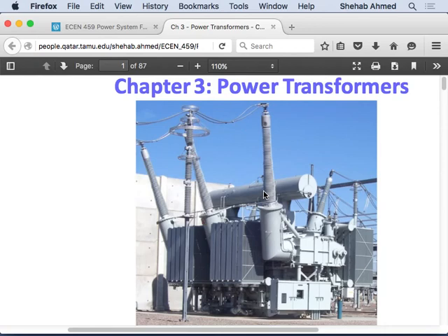And then if you do that and you add a fan around the radiators, for example, so these radiators maybe on the side, like your car radiator, if you open up your hood, you'll find your car radiator has a fan right next to it, right? So at some point, initially when you start, maybe the fan is not running. After a few minutes, then you'll find the fan running, right? So this is an additional way of forcing the radiator to cool, the oil to cool down, right? So that's why it will have 3 ratings, because of the cooling system, right?